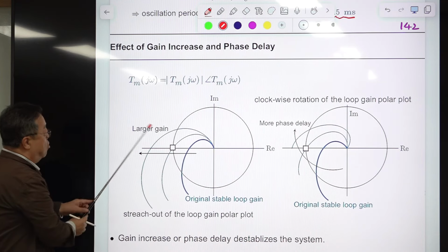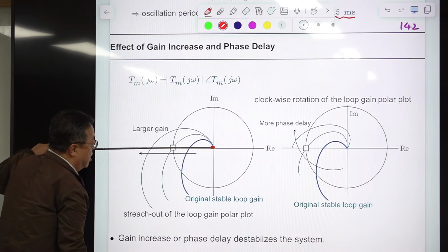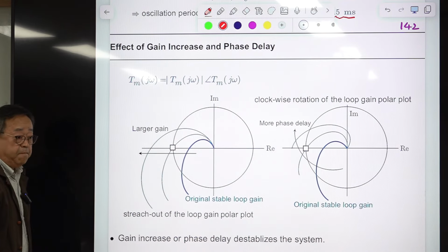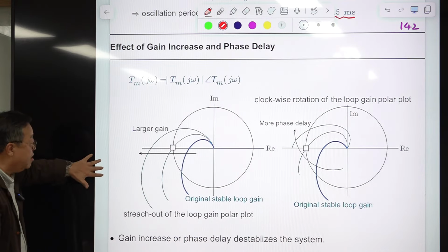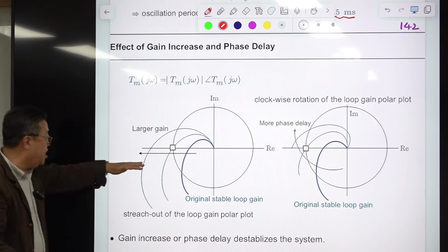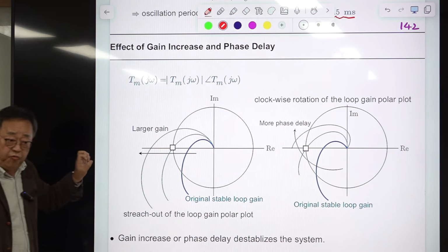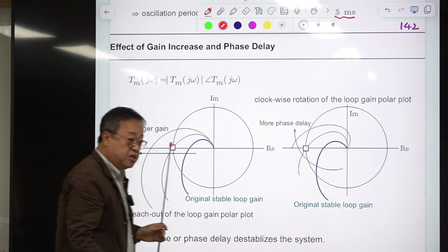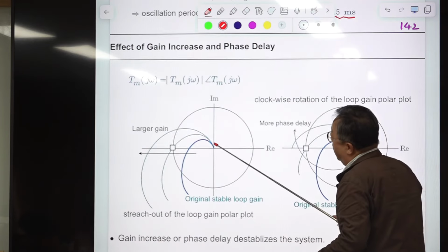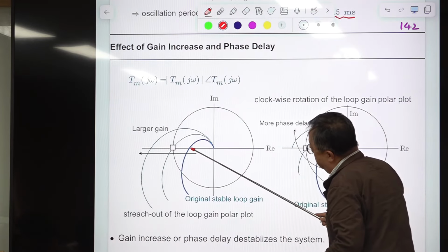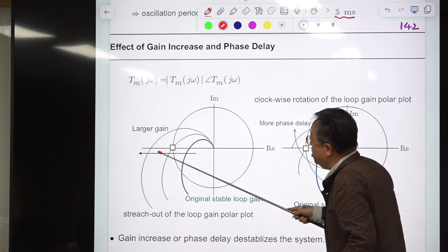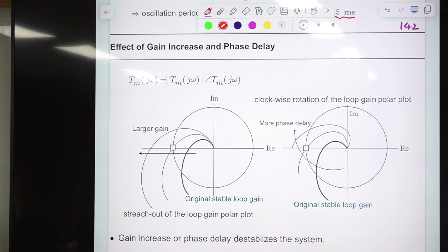The system is stable because when the phase falls to minus 180, it passes the line segment A. If we increase the feedback gain while maintaining the phase characteristic constant, then this shape remains the same. It just expands out. If the gain increases, it will be increased. If increased this much, the system becomes conditionally stable. If we increase further, the converter becomes unstable.